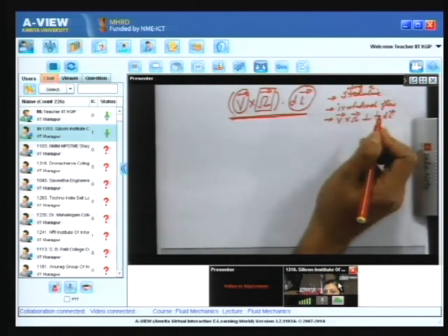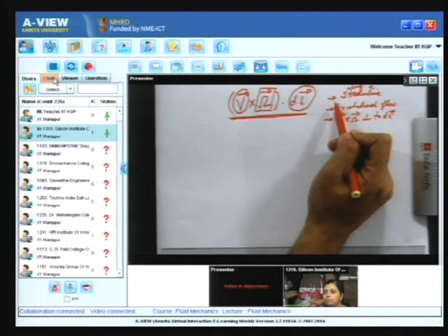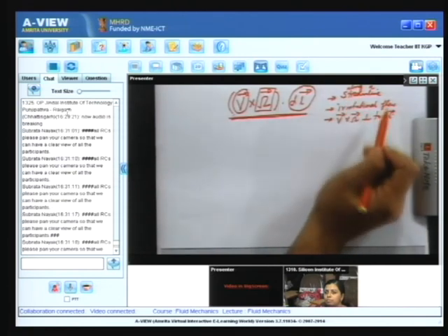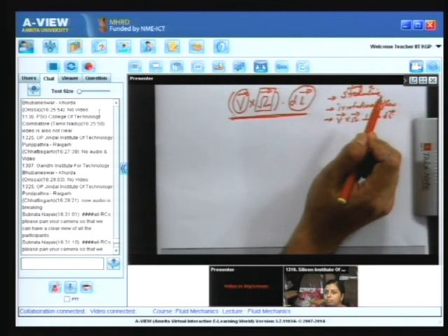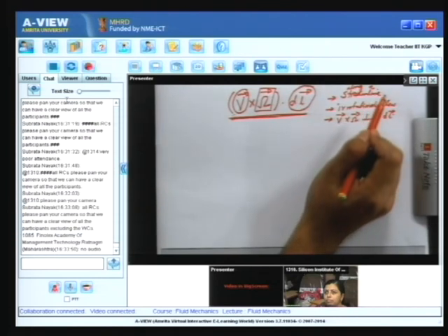So, for siphon, if you look into the textbooks where the problems on siphon are solved, the various points are located along the same streamline. If they are taken along the same streamline, you can apply Bernoulli's equation provided the inviscid, steady and incompressible fluid condition is satisfied.